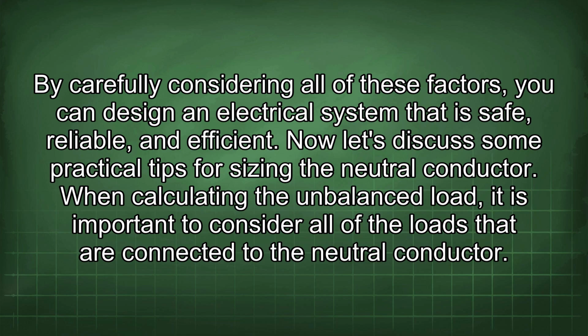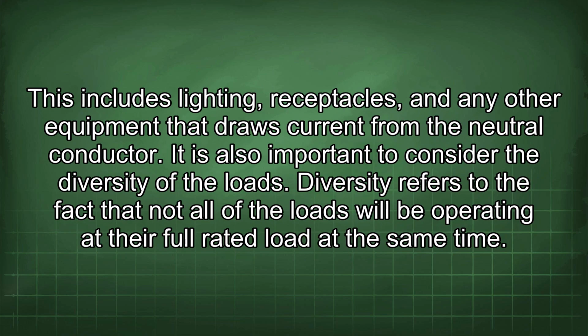Now let's discuss some practical tips for sizing the neutral conductor. When calculating the unbalanced load, it is important to consider all of the loads that are connected to the neutral conductor. This includes lighting, receptacles, and any other equipment that draws current from the neutral conductor. It is also important to consider the diversity of the loads.